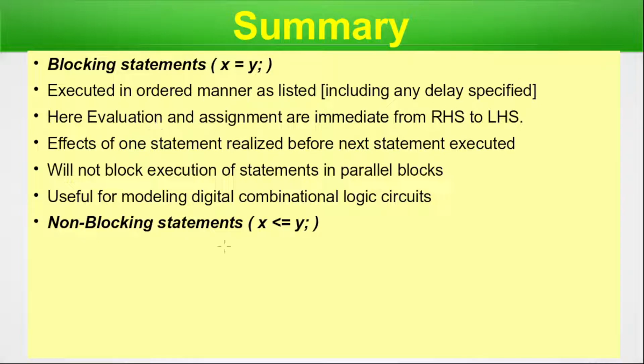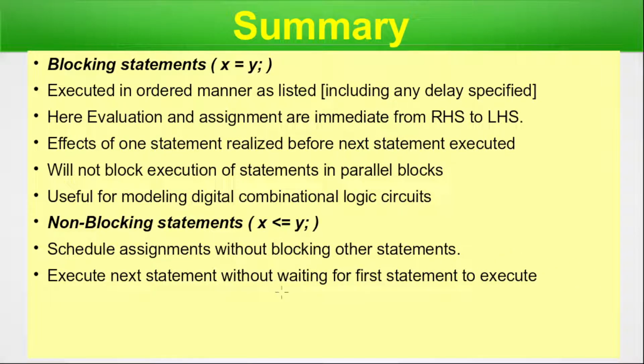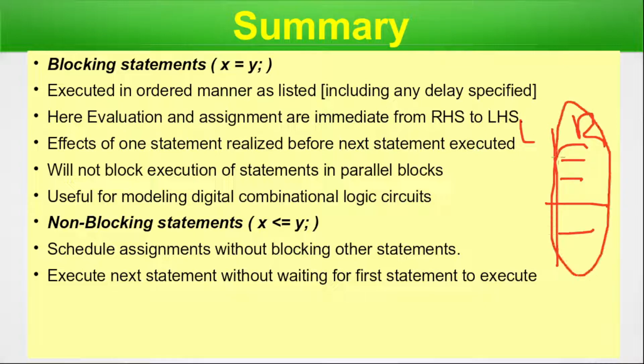Non-blocking statements, which we read out as non-blocking. The less than or equal to sign means we have a non-blocking assignment. It schedules assignments without blocking other statements. Execute the next statement without waiting for the first statement to execute. So if we have all the statements, with the separator, the LHS, and the RHS, all of the evaluations will happen, and the transfer from RHS to LHS will be done in one go.